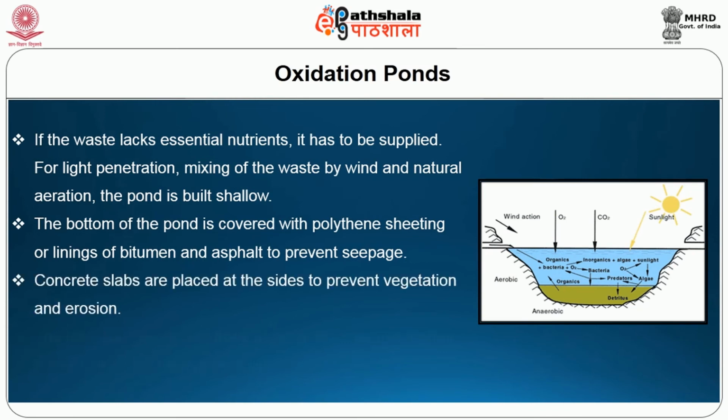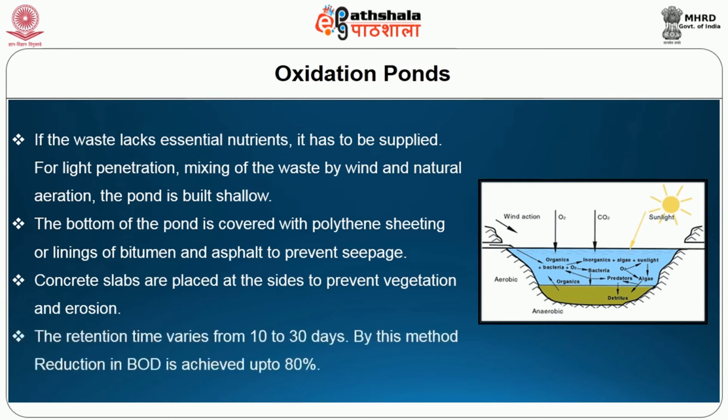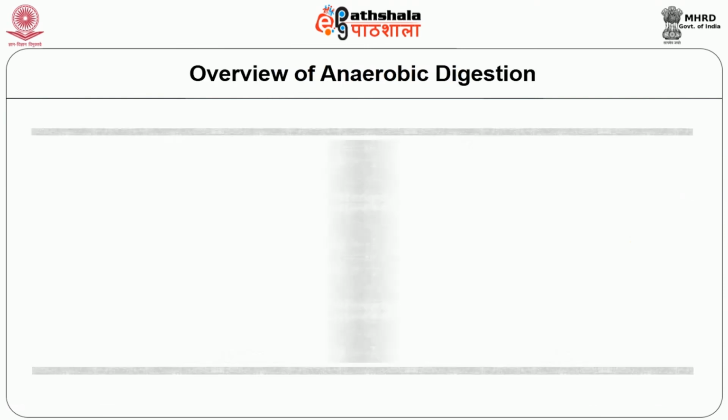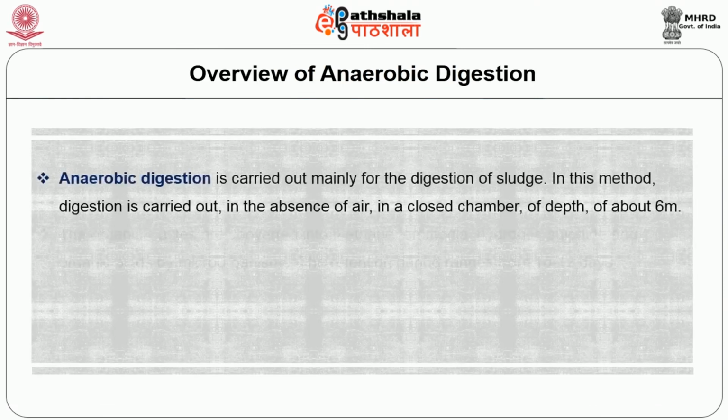Concrete slabs are placed at the sides to prevent vegetation and erosion. The retention time varies from 10 to 30 days. By this method, reduction in BOD is achieved up to 80%. We have discussed aerobic secondary treatment methods.